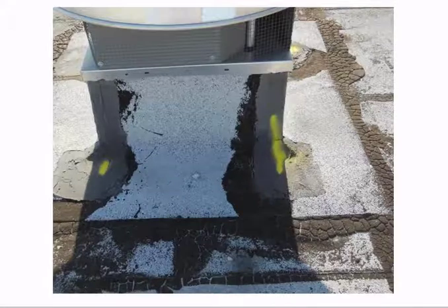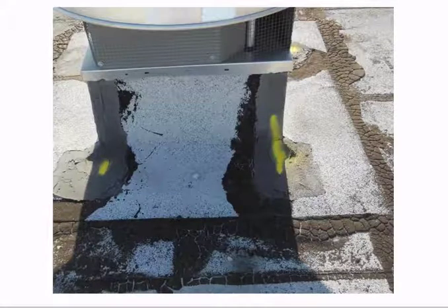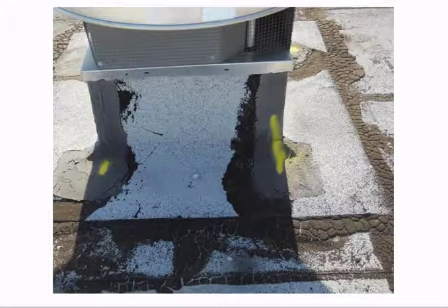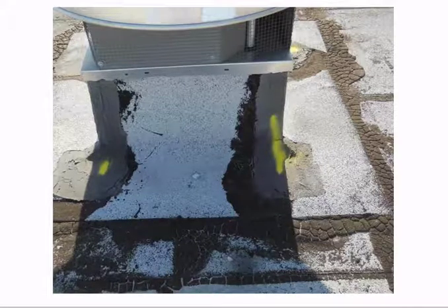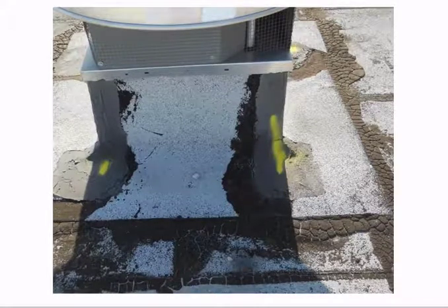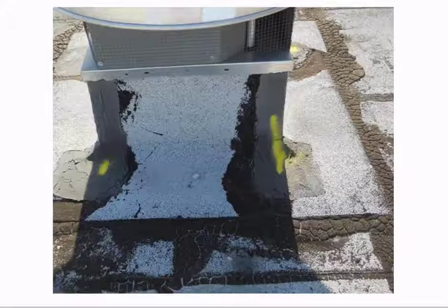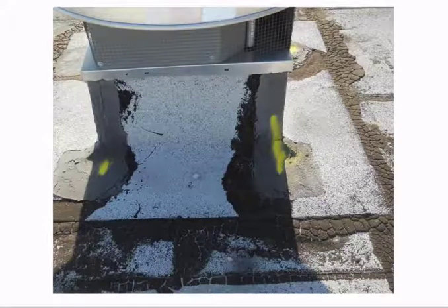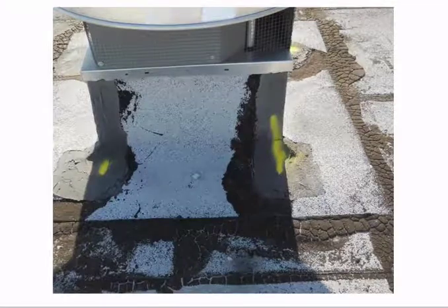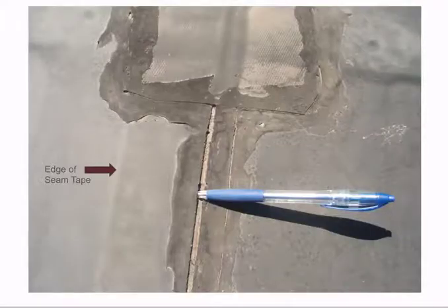What are we seeing here, Craig? Nick, here I see a rooftop curb. This is a very, very typical detail. Looks like it's a job well done. I would say they need to come back through and finish up their corners a little bit, or readdress those with another three-course system on that. Maybe dress up the base flashing around that a little bit. Yep. That's about all I see on that. It's a pretty common detail.